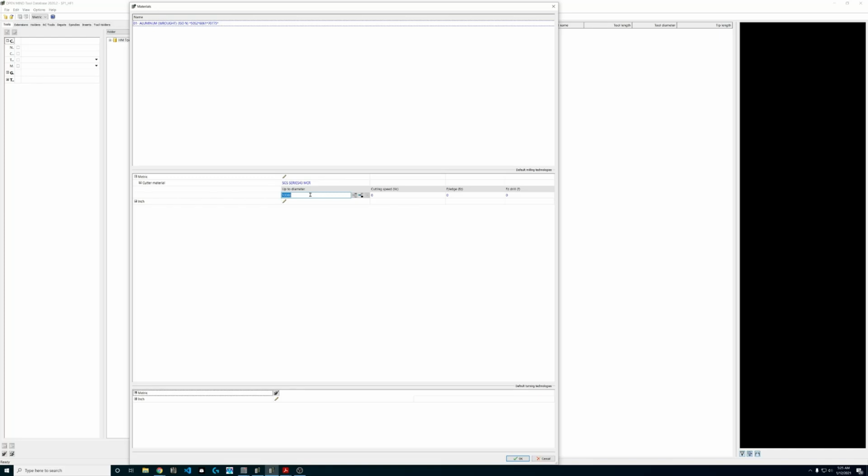If we say, okay, they tell me for a 20 millimeter tool, we're going to use the slotting data to start. Or better yet, we can use the profiling data. They actually provide some high-speed machining data as well. You need to decide which data set you're going to use, because most manufacturers provide at least one or two. Slotting has generally been the great equalizer. If you had a firm grasp on your slotting feed rate and chip load, it was pretty easy to figure out other values from that. But I like working with the profile now that I think about it. That's probably what I use most often.